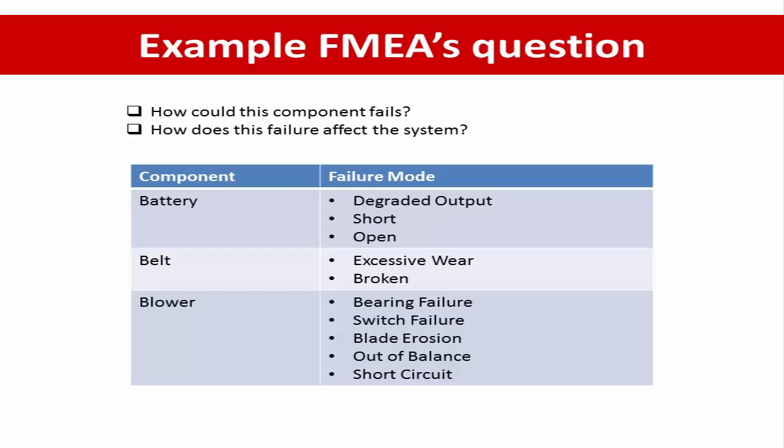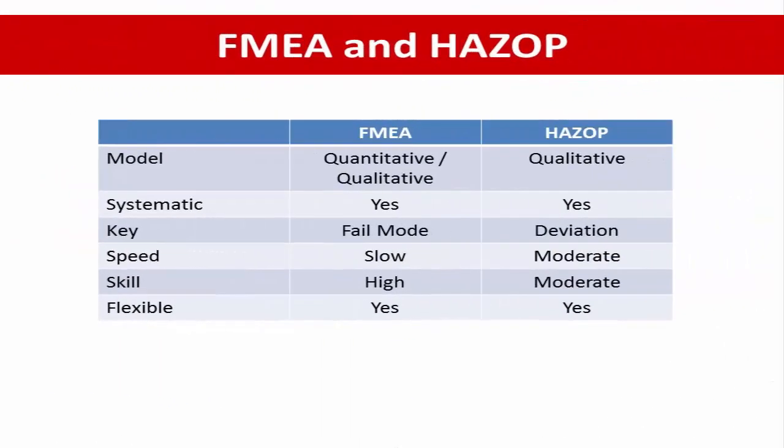If we want to compare FMEA and HAZOP in the safety engineering review, the FMEA is frequently quantitative, but it is also often used qualitatively as a hazard analysis technique. It may be used instead of the HAZOP in certain cases, and it is more equipment oriented. The comparison between FMEA and HAZOP is preliminarily shown in the table below.